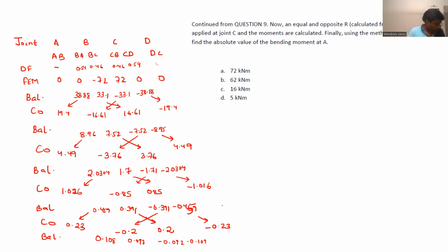This will go. Let us stop here. And one thing you should remember: when you are doing this balancing carryover, any number of times you perform it, make sure that you are terminating your results in balancing mode only. You should not keep any net movements if they are not externally available. Always try to keep all those joints in balance condition only.